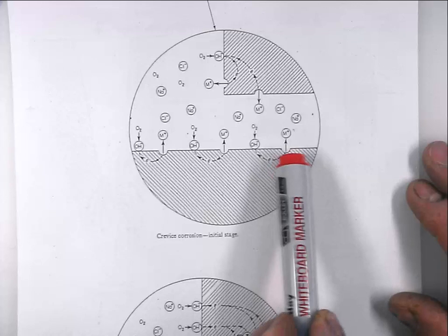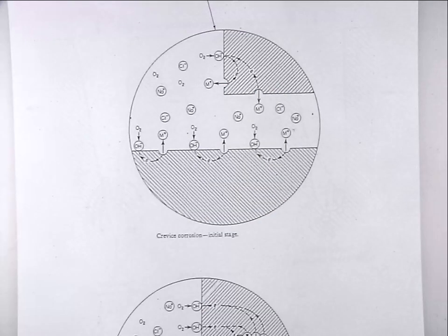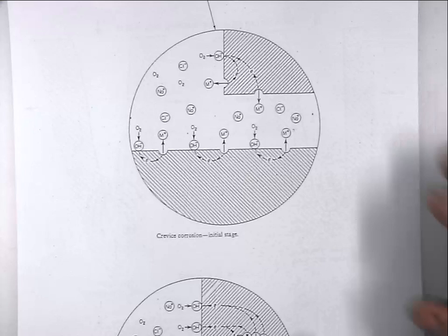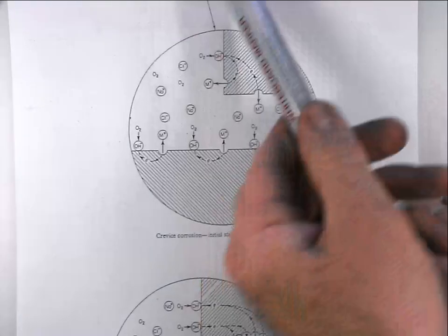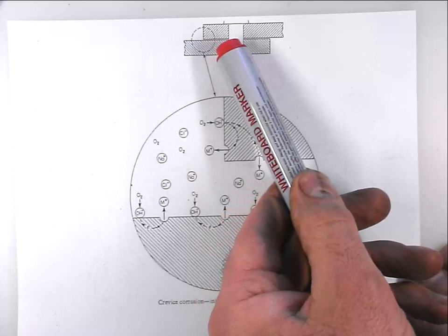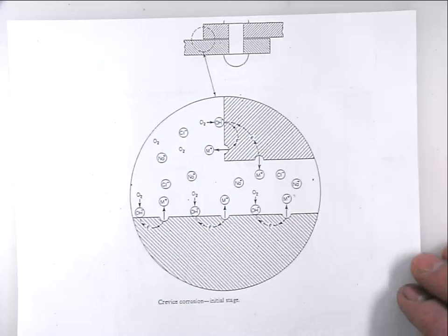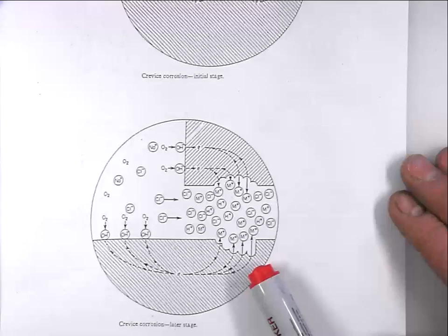Excuse me. We have the formation of chlorides there. Yeah, well, the metal ions will subsequently react, and they will react with the environment, either to hydrolyze and produce oxides, or to produce salts. Depends on what the environment is. In the case of groundwaters and things which perhaps buried pipe is going to be involved with, you're going to get carbonates and oxides. That's the sort of secondary part of the process.